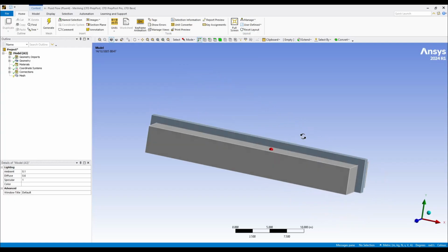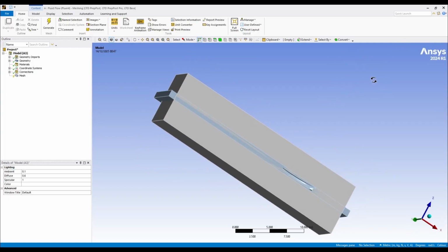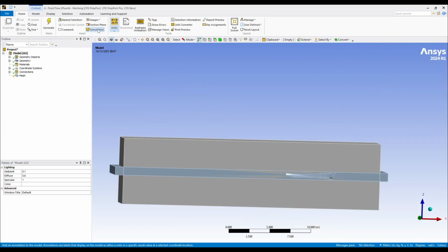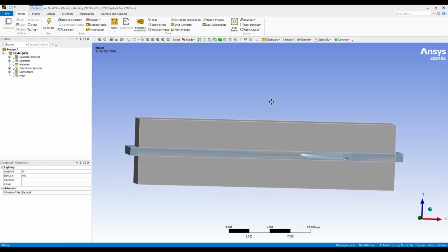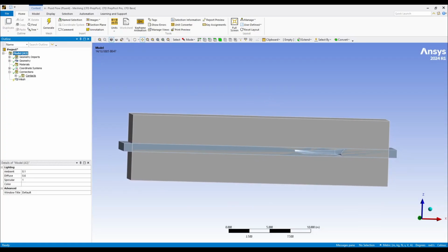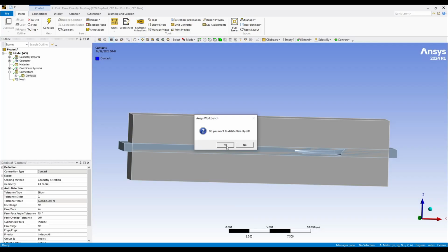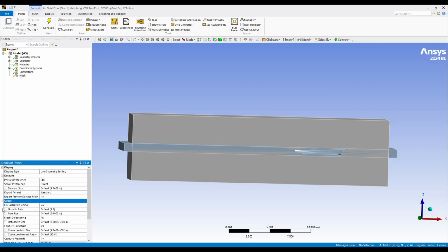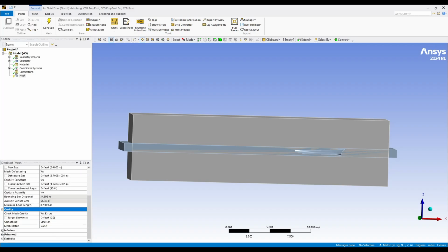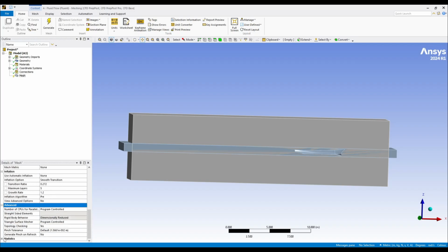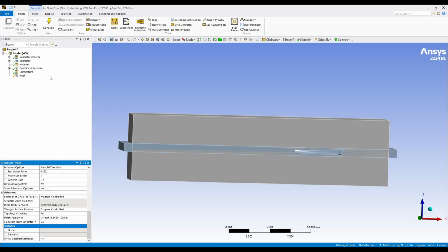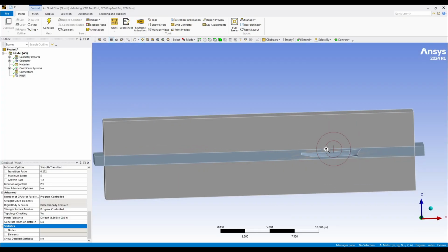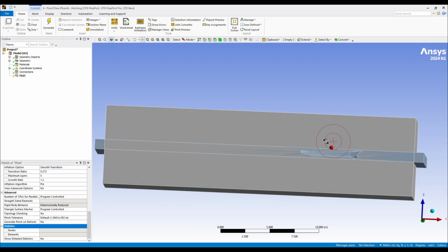Now what we will do, the first thing we can do is to remove the connections from here. We'll just get rid of the contact, or the children contact. Then in size, mesh is the most crucial part. We will just see the statistics. There is no statistics here. So first we will work with the body of influence.